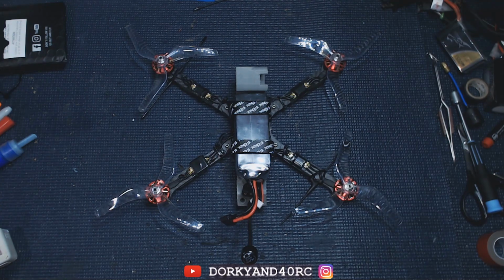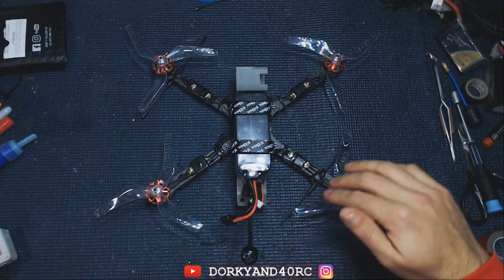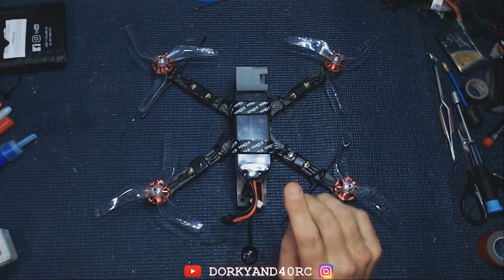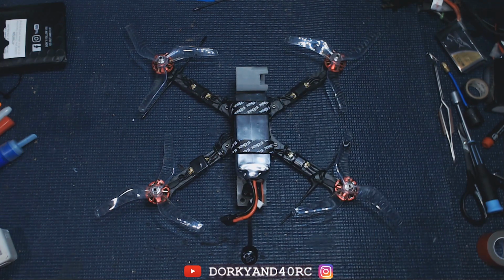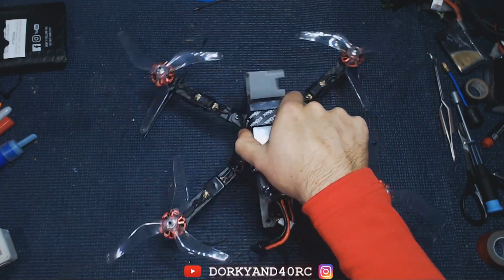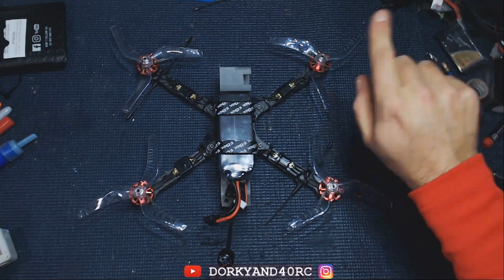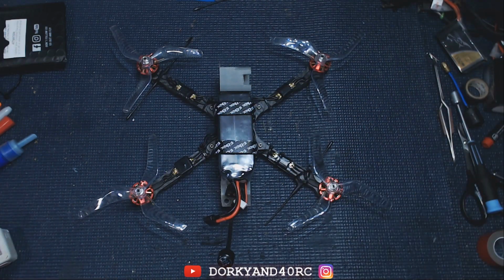Watching some live streams, some old stuff from Trappy when the diversity module came out, I decided to mount the antennas this way, mostly because I don't need a vertical and a horizontal type of antenna, because on long range type of flights, you're really just kind of doing this. You know, you're not really flippy floppy and doing all that kind of stuff. So I'm not worried about cross polarizing. So we'll have all the antennas on the same plane. Now our nulls are actually the same as well, which was, I thought, a concern, but after the testing, at least for my flying conditions, hasn't been that much of a concern at all.